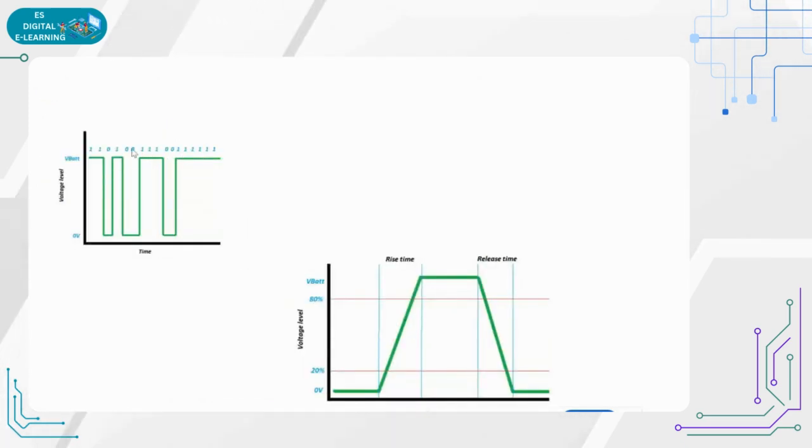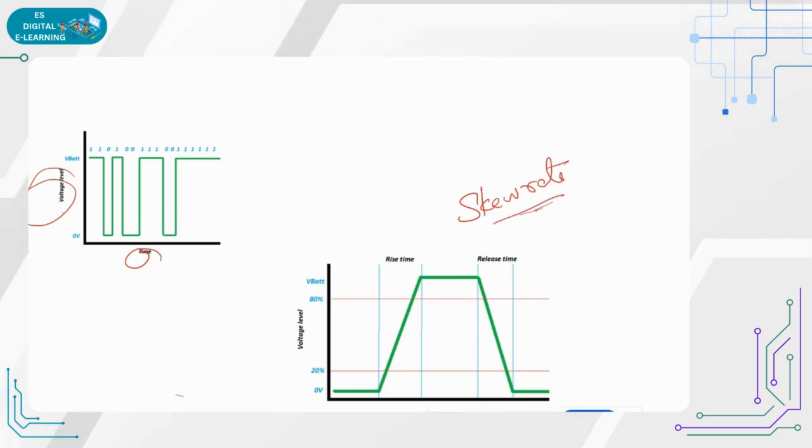Okay, so that is just the message structure, we just summarized. And coming to the voltage level, as we discussed, wherever it is rising, it will be the ones, and the fallings will be the zeros with respect to the voltage, and only with timing will the data be transferred. Okay, so this is another important point: normally there will be the slew rate. We usually ask what is slew rate. The rising time and the falling time we consider as the slew rate. This is just for understanding the subject.